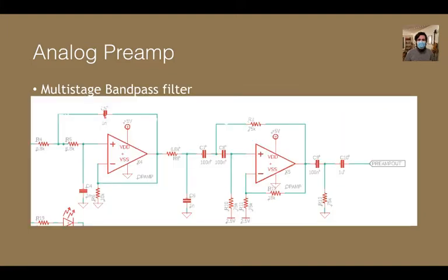And here is our multi-stage bandpass filter. It cuts out frequencies at about 20-ish hertz, as the cutoff point is at 20-ish hertz, but it still lowers the frequencies above that a bit, and we don't want to affect frequencies like 80 hertz too much, so we lowered the cutoff lower than 80 hertz. And then it cuts off high frequencies at about 12,000 hertz, in the current version.